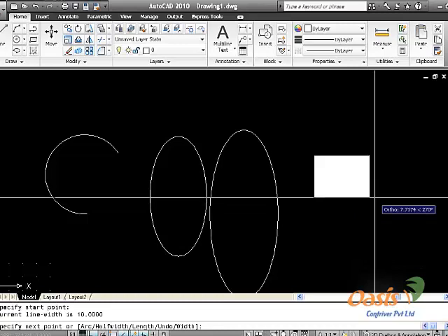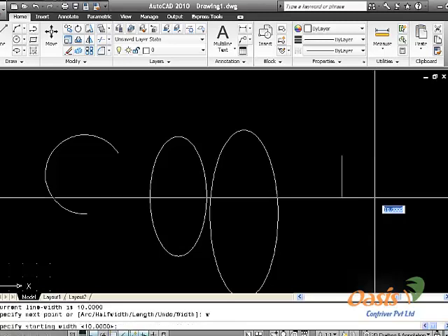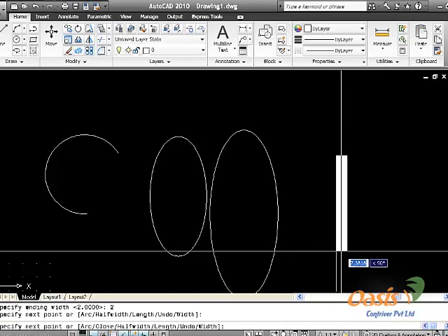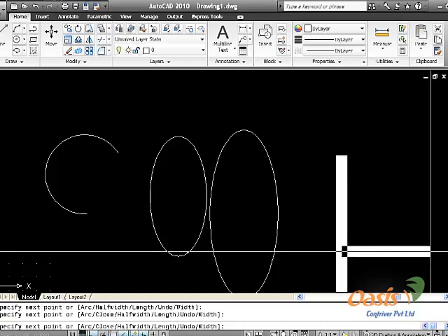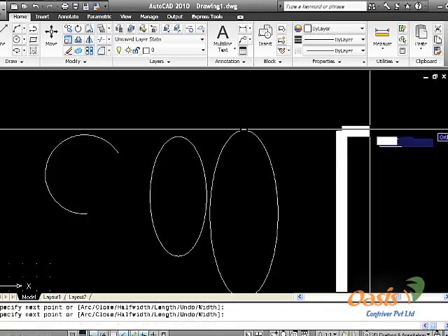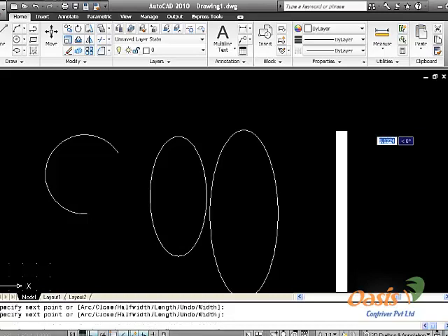Here we have priorly specified the width. So let us press W in the command window, press enter and specify another width which will be just 2, so that the line won't be this much thick. The endpoint will be again 2, so that the line will continue with the start and end point in the same thickness. It will continue drawing it. This is specifically used by civil drawing draftsmen for their walls and other specifications in drawing. And when we press enter, the drawing will be ended.